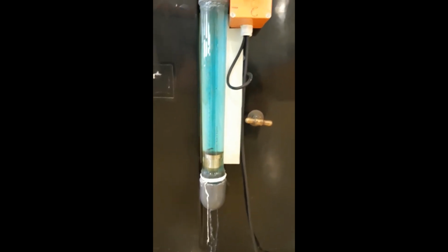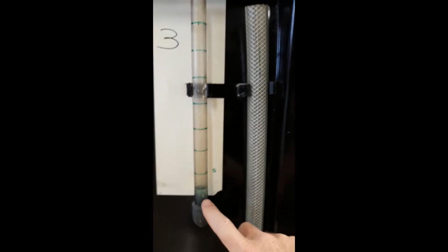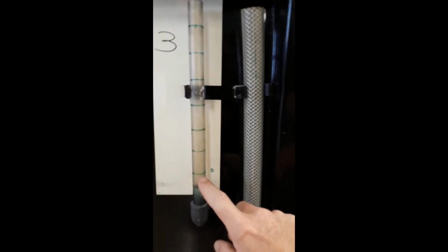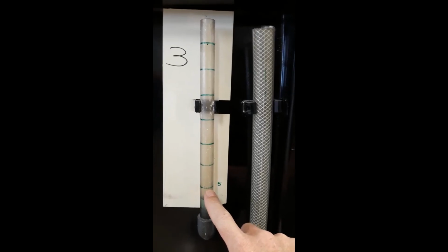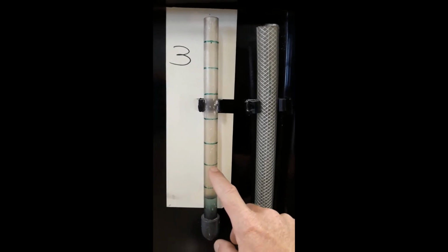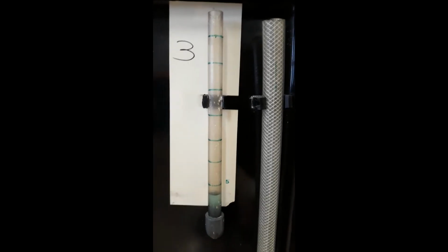To calibrate the Rotameter, we're going to put the Rotameter on reading 0, and then we're going to close this small basin with this plug. Now the water inside the basin will start to rise. And remember, these increments are marked 5 liters apart. So when the water reaches this line, I'm going to start my stopwatch. And when it reaches that line, I'm going to stop my stopwatch. Then I'll know how long it took to fill 5 liters of water.